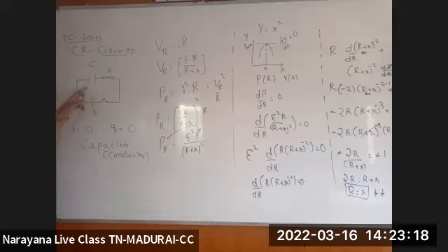Accumulated charges act like a resistor or opposition. As there is no opposition, the empty capacitor is acting like a pure conductor. By then the maximum current will flow in the circuit. What is the maximum current flowing in the circuit? Net EMF by net resistance.